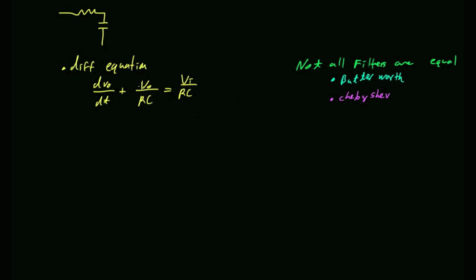Okay. So then what we did is we took that and we used that to generate the characteristic equation. And the steps we did were we looked at the coefficients for each of the terms in the differential equation. And on the output side, we just set it equal to 0. So we said, suppose there's no output. So here the coefficient is 1 times S. And here the coefficient is 1 over RC. And if there was a second derivative, it would be S squared. If there was a third derivative, it would be S cubed, and so on. Basically you just pulled out the coefficients, and that becomes your characteristic equation. You solve the characteristic equation, and that's how we got, for example, the step response.